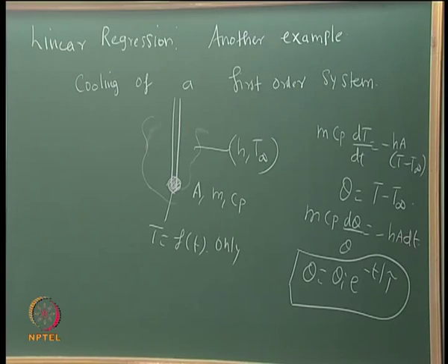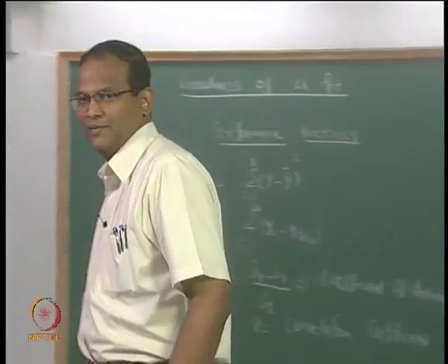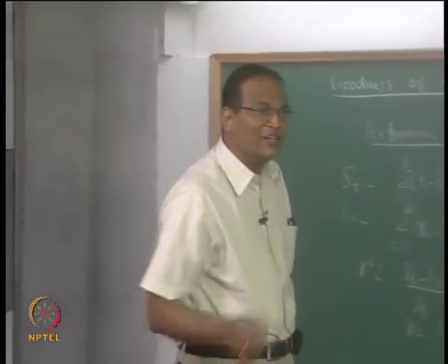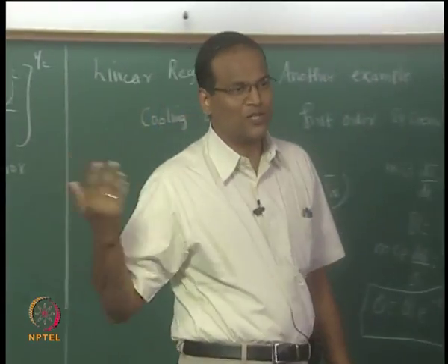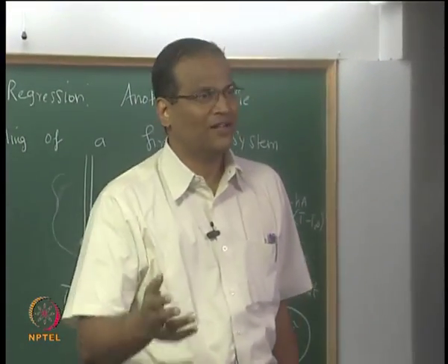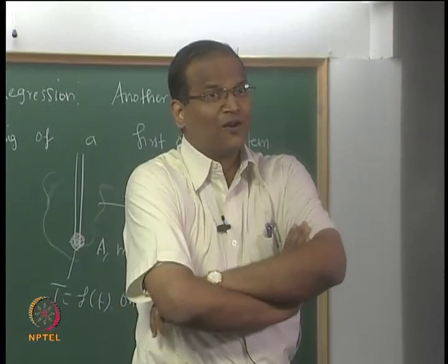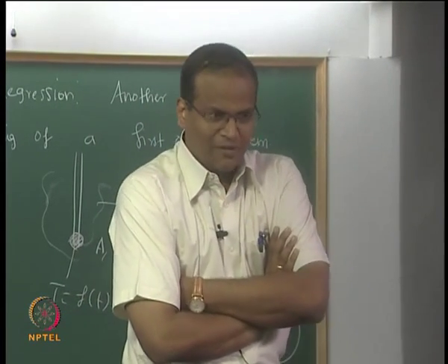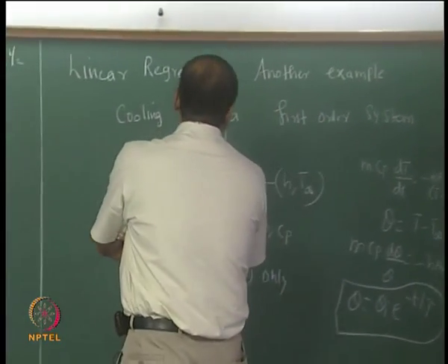Unfortunately, T infinity, the temperature of the surrounding water, will start going up because the heat is going there. Now we can model it as a second order system and work out the solution, but this is not a heat transfer class. We can do that in a heat transfer class. That is a second order system where T infinity keeps changing, but in this case it is relatively straightforward. We can keep T infinity constant.